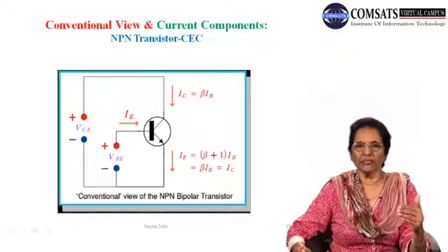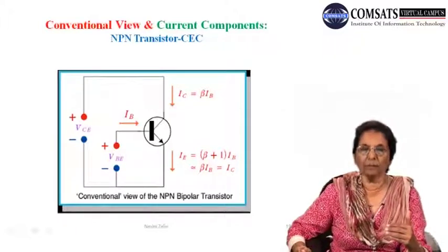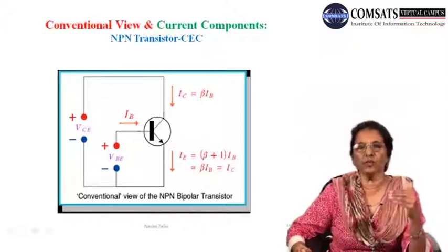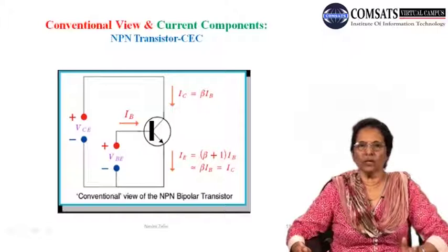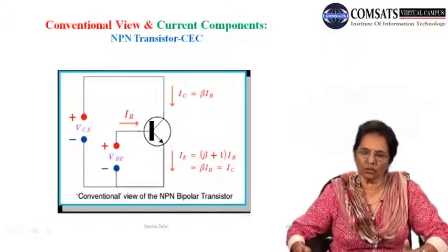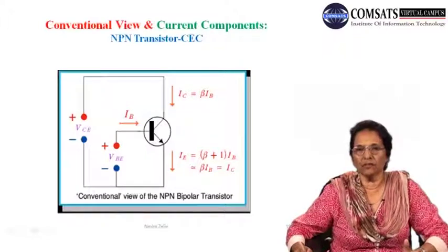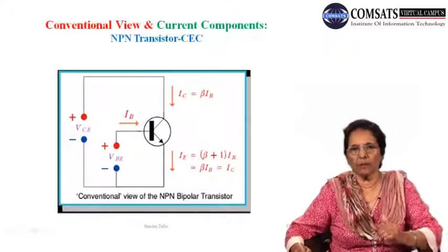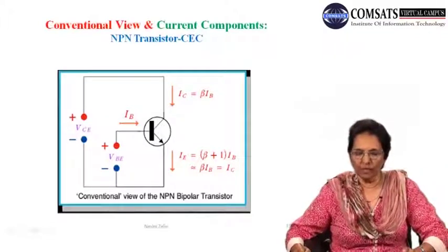As you look at the polarity of the input voltage, the current would be towards the base, and in the loop, following Kirchhoff's current and voltage laws, the current would be moving from base to emitter and back again through the input loop.